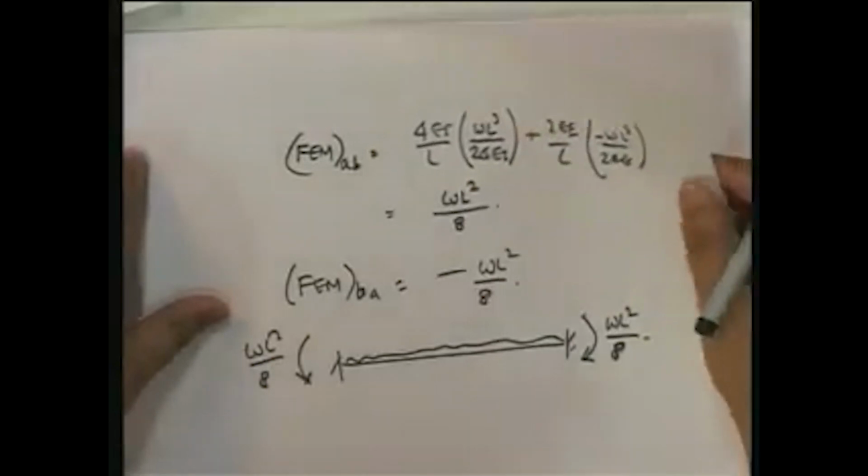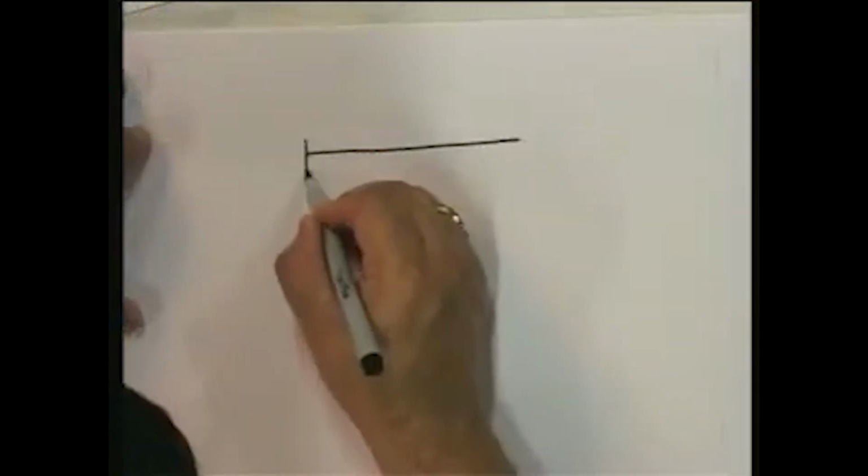Let me finally do one more problem and convince you that I have not constructed this to make life complicated for you. It is just that any loading you can always take, put that same loading on the simply supported beam, find the rotations of the two ends, and put the negative of the two rotations into the slope deflection equations, and you will get your fixed end moments. Okay? I am going to do a final one before I show you how this is going to get used.